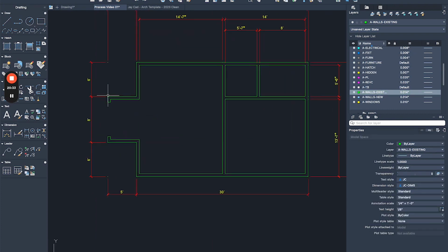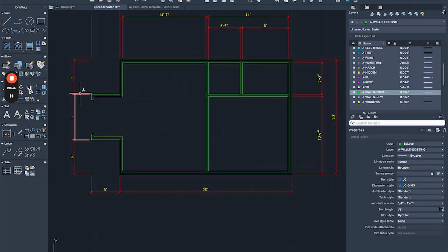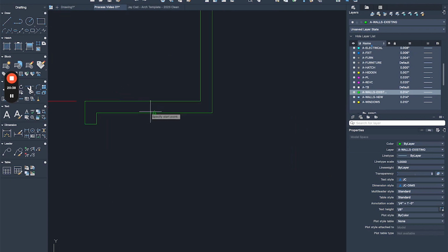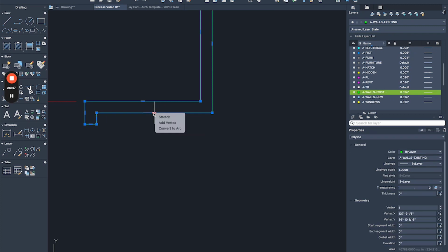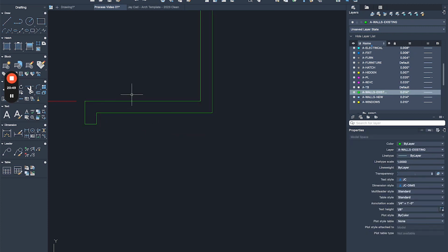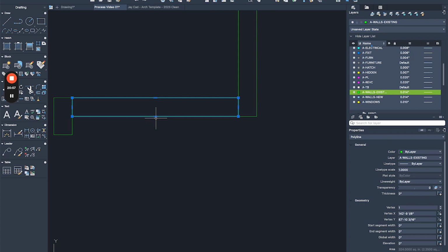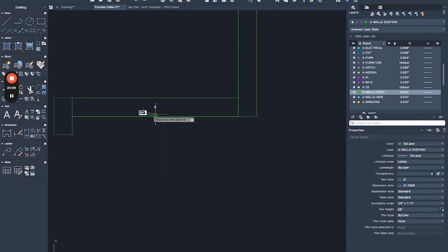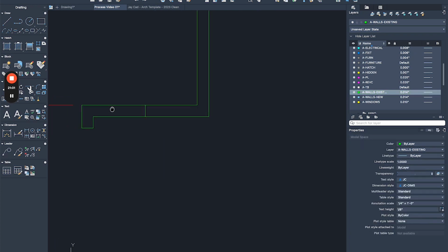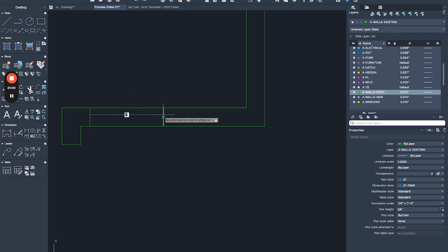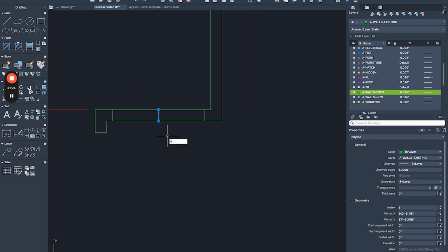Okay, so this is looking good. I'm going to start adding more openings around. I'm going to add one here from the middle point. I want to add it literally in the middle between these two areas. If I use this middle point or this middle point, it's not going to be exactly in the middle between the walls. So I drew a reference polyline, and the middle point is the one that I want to get from here. Then I'll get rid of it, and now I'll offset 2 feet to the right, 2 feet to the left, and get rid of it.